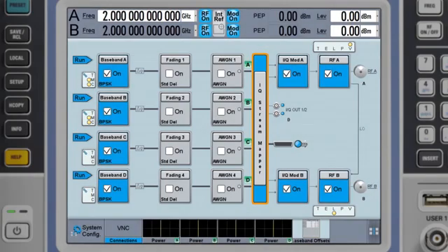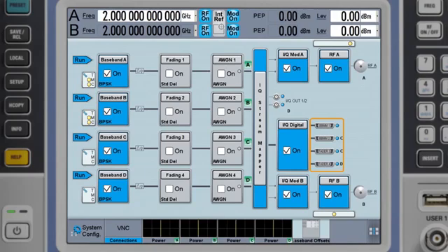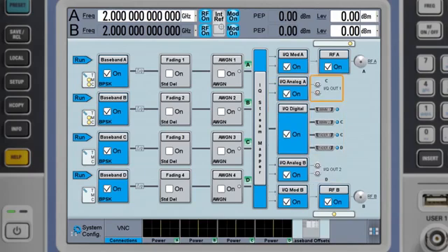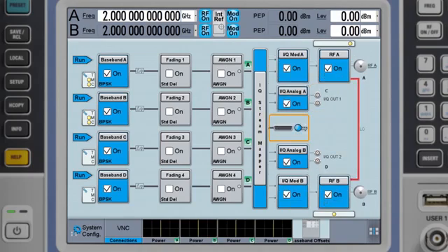One stream is directly output at RF chain A. The other stream is directly output at RF stream B. Stream C and D are output at the digital interface and at the analog interface. All the channels share the same local oscillator, so there is no difference.